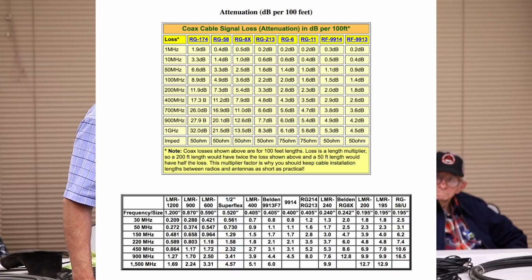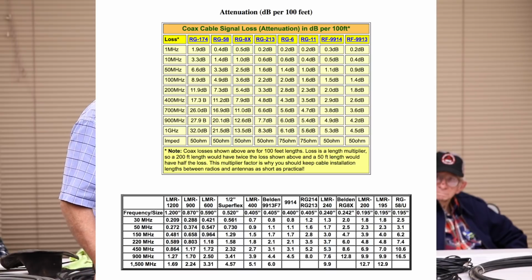It's less than 1 dB loss per 100 feet. So at that point, I'm just worried about my half wavelength length. I'm concerned about the power handling, all that kind of stuff, and if it's a quality cable that's UV resistant, all the normal stuff that we do.